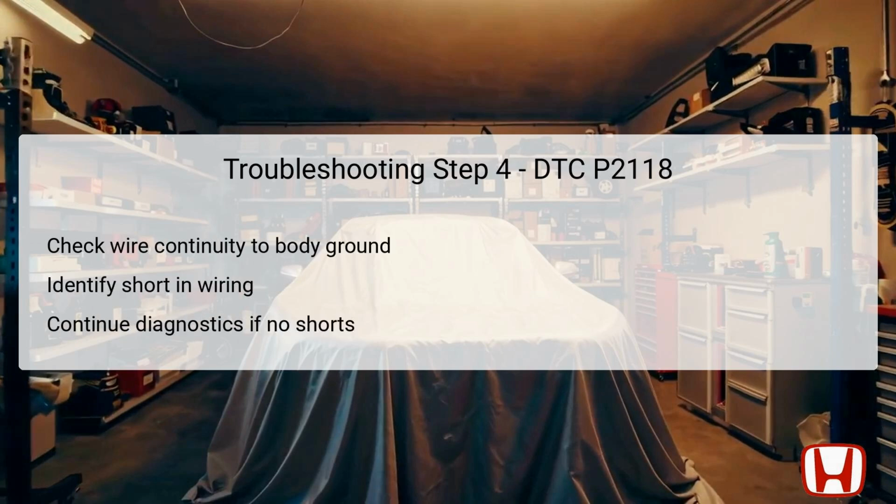In Step 4 of the troubleshooting process, you will further evaluate the MTR1 and MTR2 lines for shorts, this time checking against a body ground. Again, ensure the vehicle is in the off lock mode with the PCM and throttle body connectors disconnected. Focus your attention on continuity between throttle body 6P connector terminals number 1 and number 2, and the vehicle's body